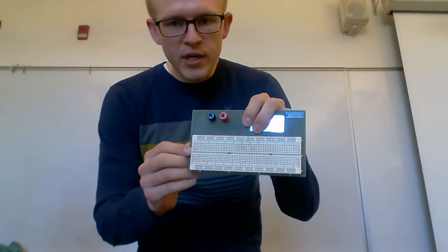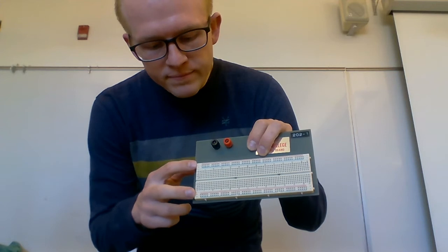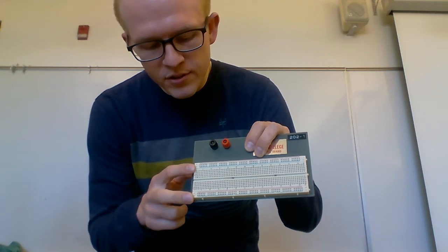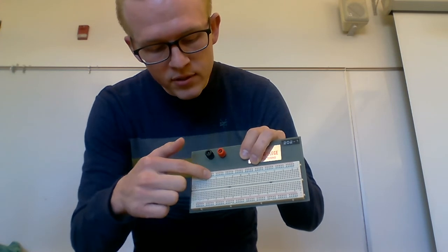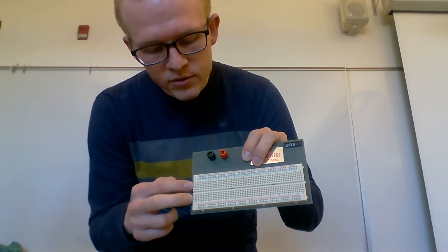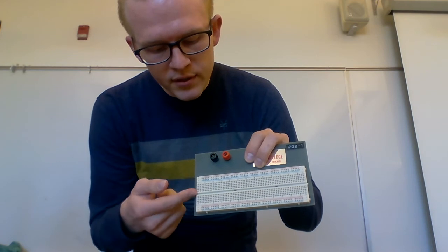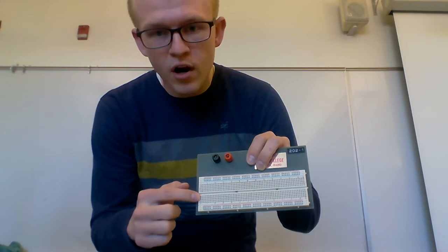this is a breadboard right here, and the red lines are for power, the blue lines are for ground, and up here and at the bottom these are connected horizontally like this, and then the 2 sections in the middle are connected vertically with this trough in the middle that separates them. So if you want to connect this whole thing, you have to jump over this trough here. That's it. Next slide.